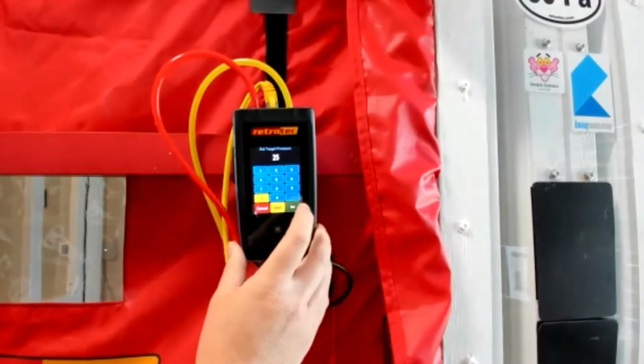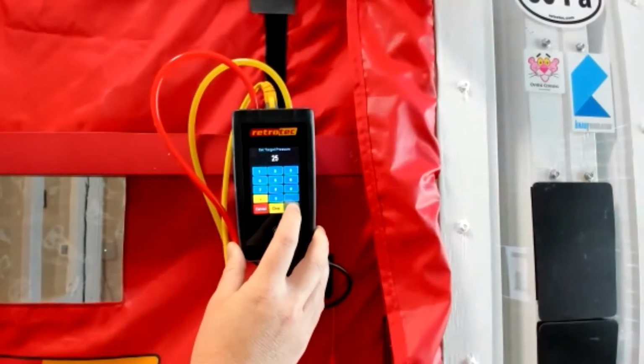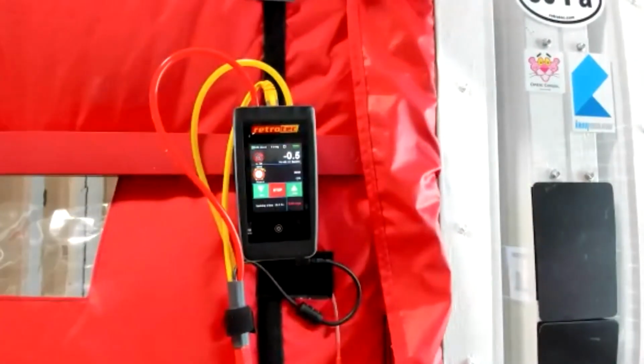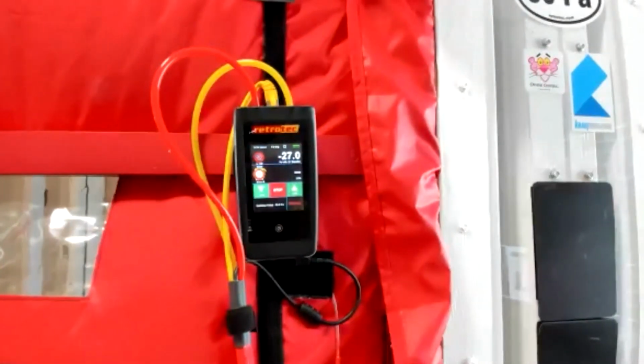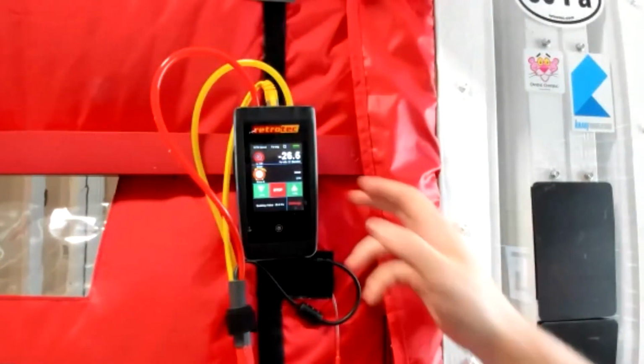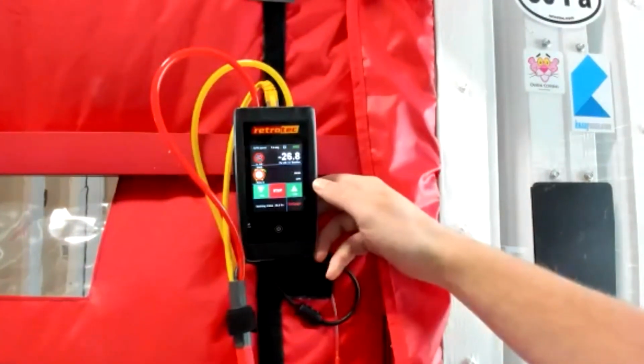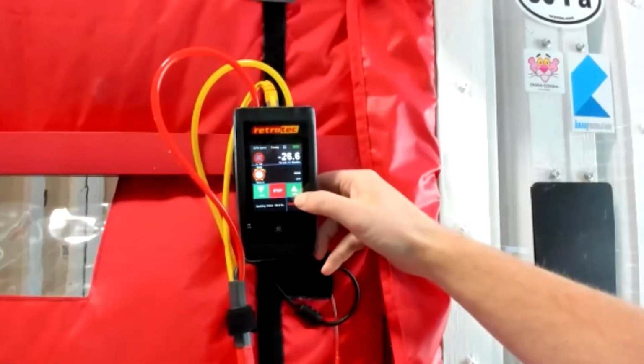But yeah, I'll just set to 25 and it's set. The fan's going to crank up. So it's dropping from that 30 down to 25. And let's say I walk around, everything looks good. So I can either stop the test and then re-enter 50 pascals, or I've got these buttons on the side here. You see these green buttons on the left and right of stop. These allow me to jog it up by 5 pascals. So I can just jog it up.